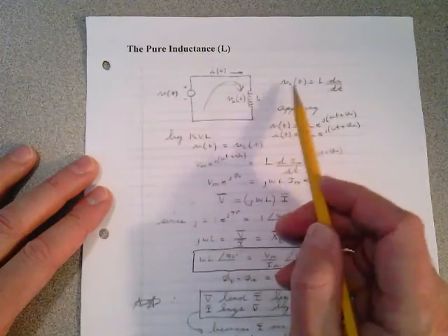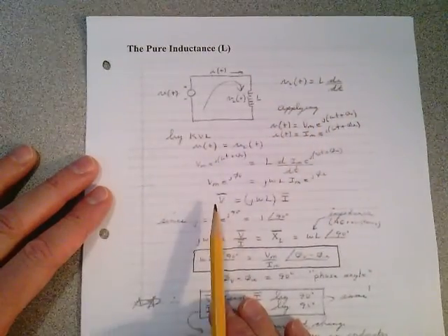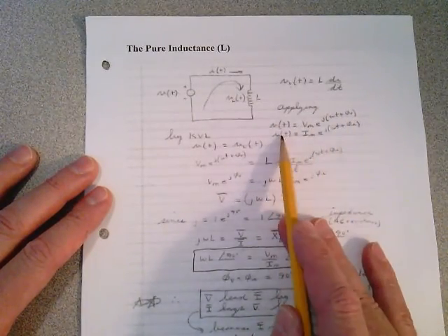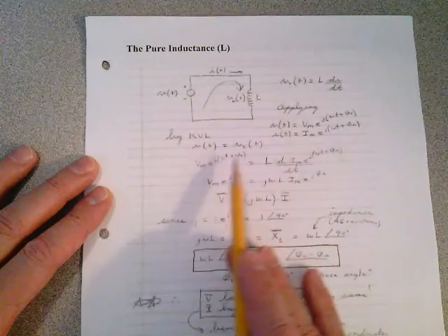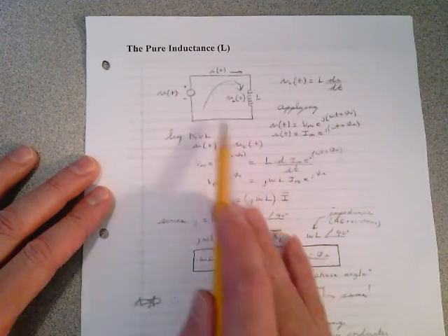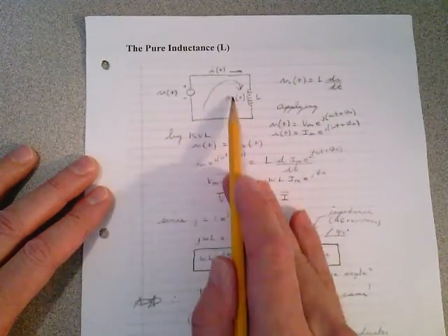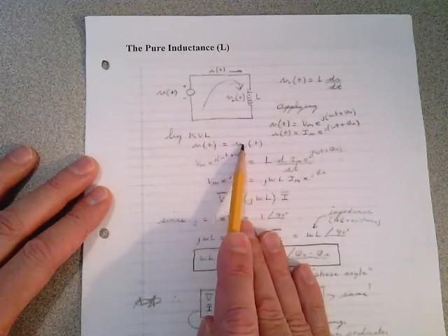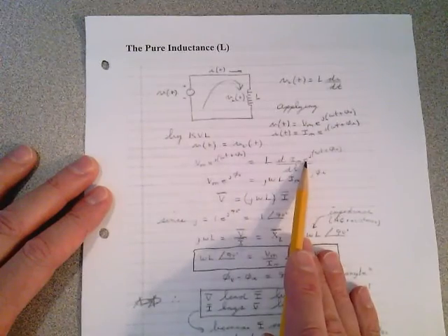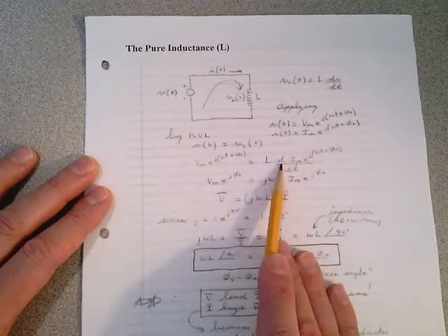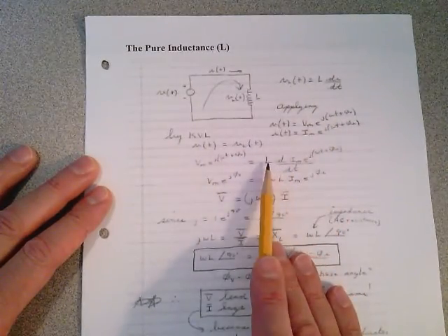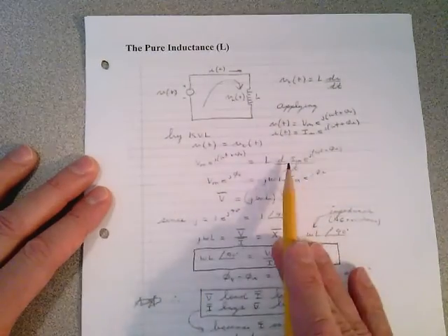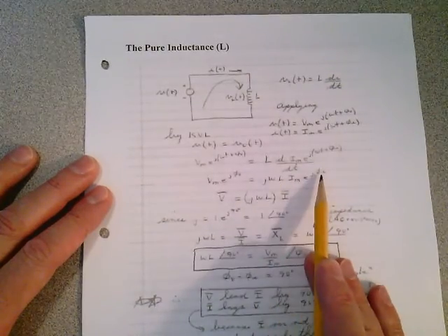Voltage across the inductor with respect to time is L di/dt, and we're just going to apply the voltage with respect to time. There's the complex voltage form. Here's the complex current form. By Kirchhoff's current law, and by Kirchhoff's voltage law, the rise has to equal the drop. I'm making the substitution, but in order to find the voltage here, it's L di/dt. I have to take the inductance times the derivative of the current with respect to time. That's a simple derivative, and you get this.